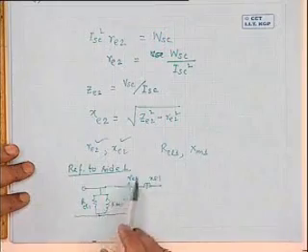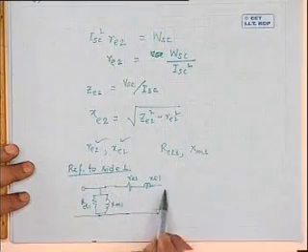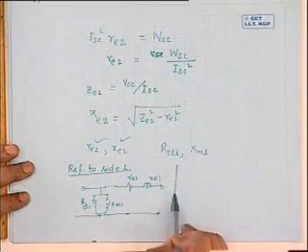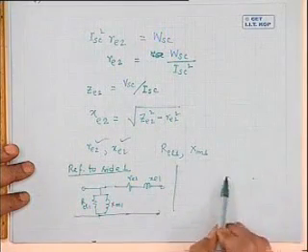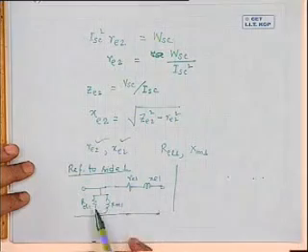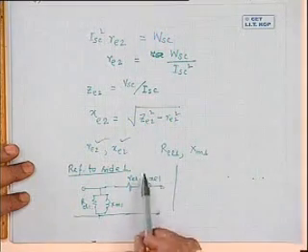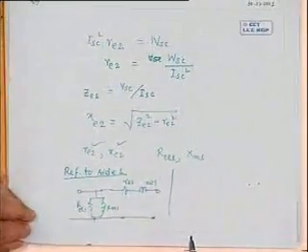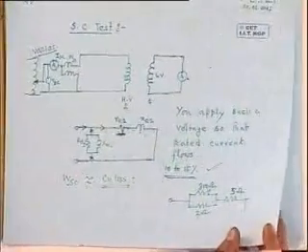I should write here RE1, XE1, so that I know how to transform this. And this will be the equivalent circuit referred to side 1. Similarly, while drawing the equivalent circuit referred to side 2, this RE2, XE2 will be intact there on that side, but these things will get transformed accordingly. So there you should be a bit careful before further proceeding with your calculation.